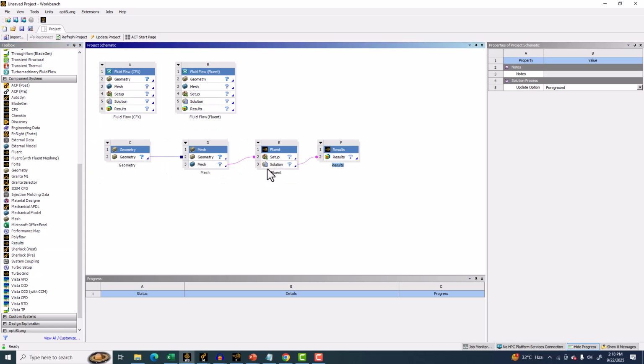Okay, so both of them have different benefits. For example, I can make two geometries and then mesh them in one single window, or maybe the geometry is the same, but I want to make different meshes and compare the different results. So there will be three meshing apps and three Fluent apps, as containers, and then I can compare all three results in one single container for CFD-Post.